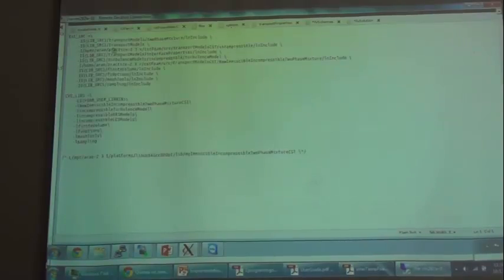And in the options, you will be accessing the two header files, the two libraries which cstFoam was accessing. One was the immiscible incompressible two-phase mixture, the modified library, and this in turn will be pointing to the other incompressible two-phase mixture library that I had modified.